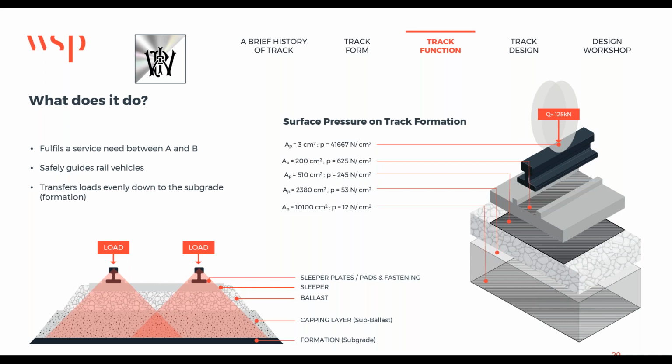It provides the basis for having good track quality. That reduces maintenance interventions and avoids premature renewal. Nothing too rocket science about this. Can't be too stiff, not too soft. Too stiff and the rails will corrugate. Too soft and you won't be able to keep a top on it and it'll feel pretty ordinary for the poor passengers that are travelling along it. In fact, severe track geometry problems often have formations with poor stiffness characteristics as a main contributory factor.